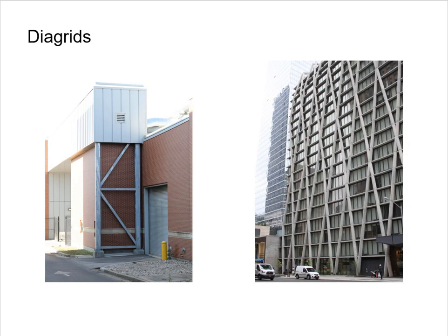There is a structural system called a diagrid that looks similar to a braced frame but is really a rigid frame. Braced frames all have horizontal members, so the system looks like triangles. When the system is made of quadrilaterals, it is called a diagrid. The diagrid requires rigid connections to make the frame stable, so it is actually a rigid frame.